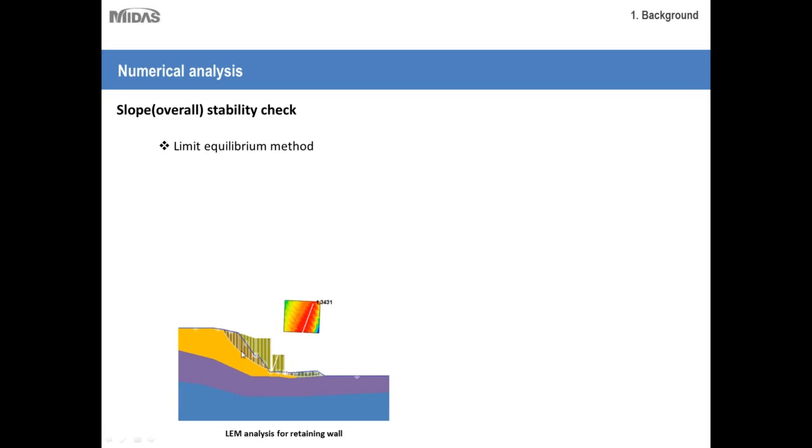So they are like rectangular strips, and we define a grid set which has different radii, but passing through a given point, and then the program or whatever software you use would consider all the permutations and combinations to check which of the given radii has the minimum factor of safety, or will be the first one to fail. So we have to define this grid in advance.